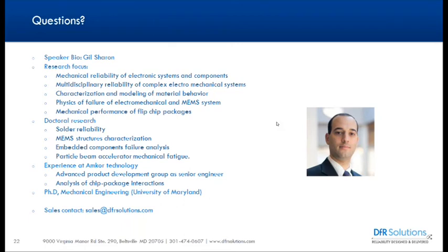Now, if it's super, super soft, it's not going to matter. If it's like the stuff that we see sometimes in power modules that is really soft and you can basically deform it just with your finger when you touch it, it might not even be a problem. But you can do an analysis on it. You can see if it moves or not. But sometimes those super soft silicones are just not enough to do the mitigation for vibration and shock. So you kind of have to make sure there's a trade-off here.